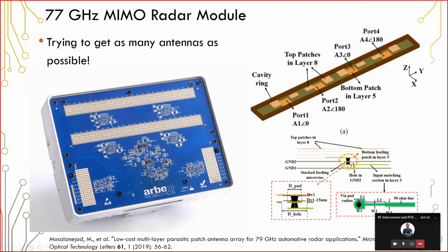Now, the caveat here is that with these stacked microvias, one of the reasons that you might want to use stacked microvias on very thin dielectrics is because when this via is very short, it doesn't look like a transmission line. And so the signal that's incoming essentially only sees the input impedance from the destination transmission line, and the vias look partially invisible. Okay, so this is a consequence of short transmission lines. Essentially, these vias act like short transmission lines.